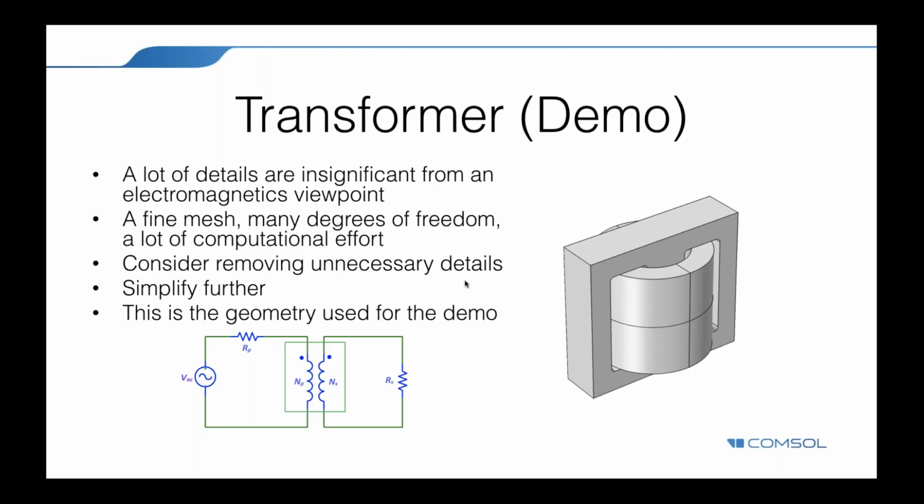The primary winding is connected to a primary resistor, RP, as you can see in the figure, and the AC voltage source, while the secondary winding is connected to the secondary load resistor, RS, as shown in the figure. The model is solved in the time domain for a line frequency of 50 Hz. Several important design parameters, such as the magnitude of the input voltage, the line frequency, the number of turns in the coils, and the coil resistance, are parameterized and can therefore easily be changed.